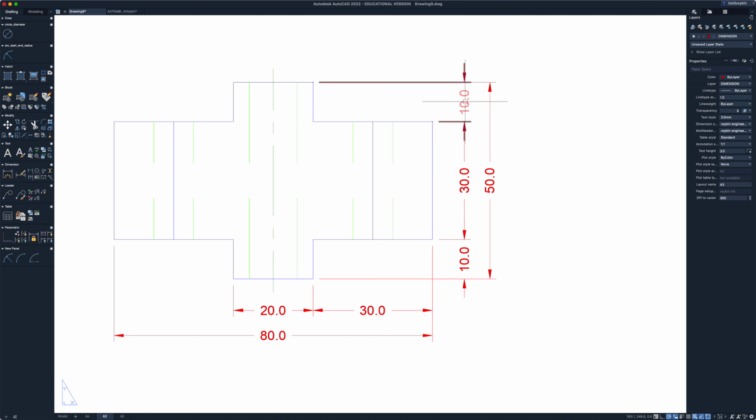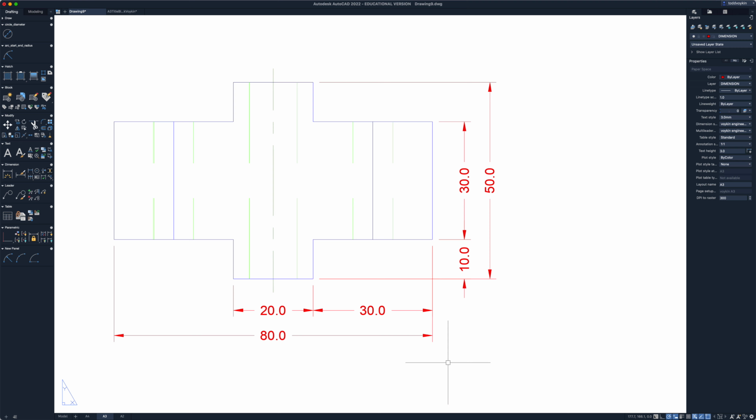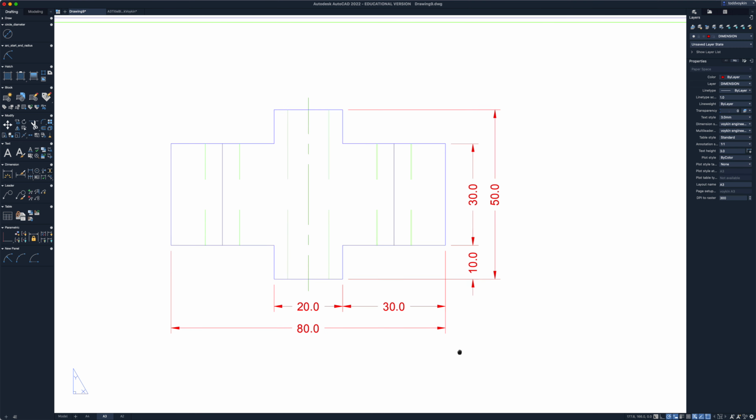And at this point I can eliminate either this 10 or this 10. So if it's myself right now, we've already got this overlapped line right here. So by eliminating this one, I'm not going to delete that, and we're going to end up using this line right here. This center line is a line of symmetry. So I'm going to delete this top one. Okay, and that looks pretty good for the top.